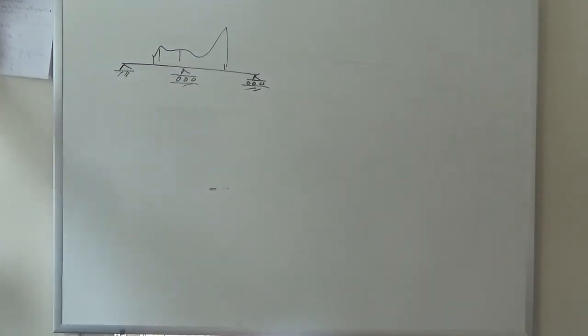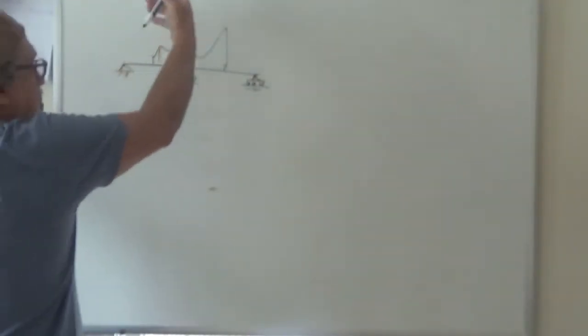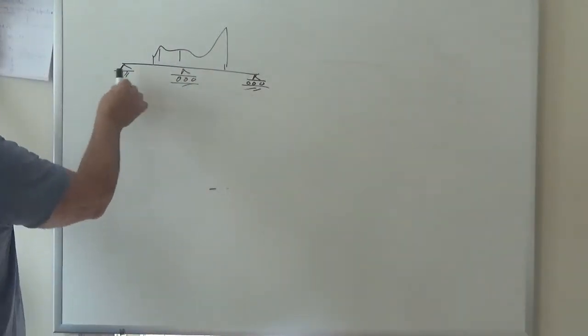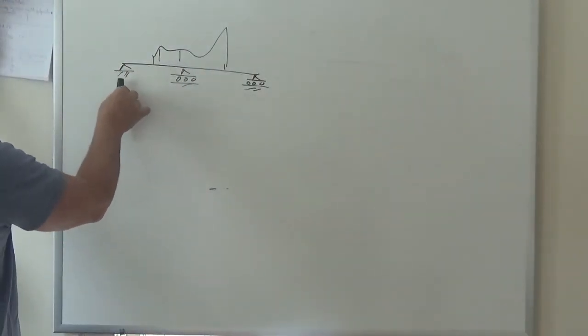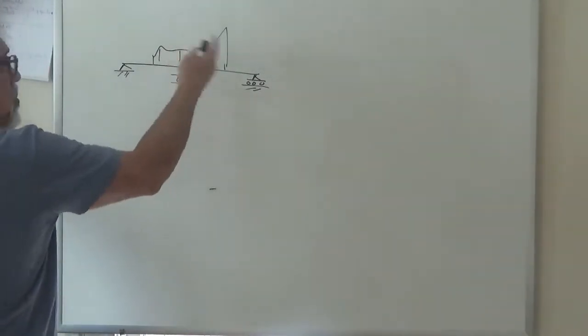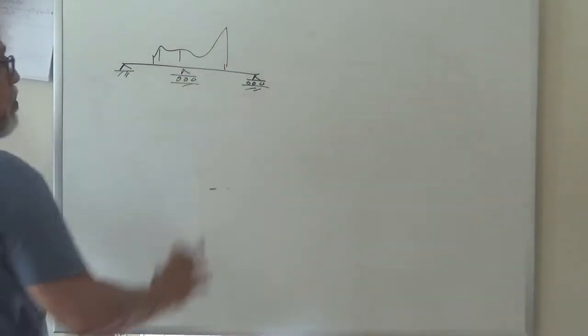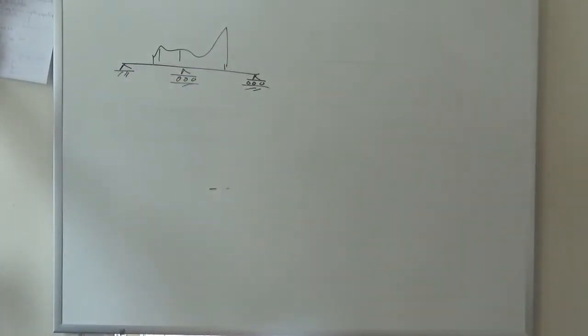When I say solve it, let's, for example, draw the shear and moment diagrams. We cannot do that from statics only because, of course, the horizontal reactions are 0 when I'm talking about beams, so I don't count the horizontal. I would say there are 1, 2, and 3 reactions, and we only have 2 equations of statics, right? Or you could say there are 1, 2, 3, and 4, and we have 3 equations of statics. So we have too many reactions, we can't solve for them, right?